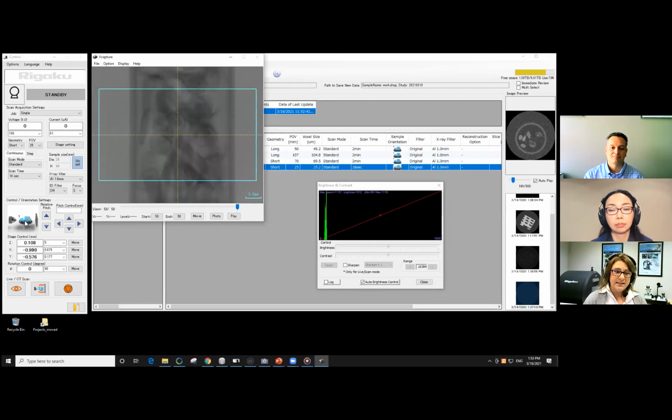If you still can't see it, you can enhance it. So I did an experiment with some carbon fiber reinforced polymer where iodine was used to soak into a crack, and then she could resolve that crack quite easily and look at the orientation of those cracks in 3D. So you certainly can, but it's good to have an idea of how big the damage or the cracks you want to see are. And just a quick couple of scans can get you there.